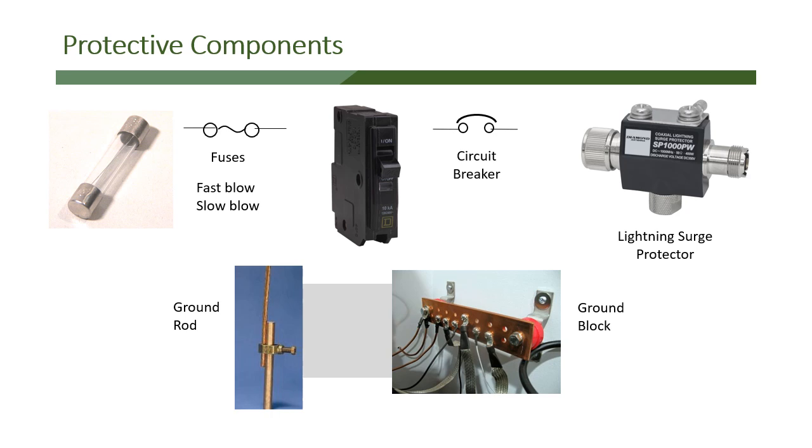Inside of a radio shack, if you have multiple radios, we always tie them back to one ground plate, one central ground. Again, you'll learn later why we do that. But we only tie everything back to one ground plate in a shack when we have multiple radios to protect the radios from any damage. The average person who only has one radio doesn't really need to do this, but we do it when we have multiple radios in the shack and multiple devices.